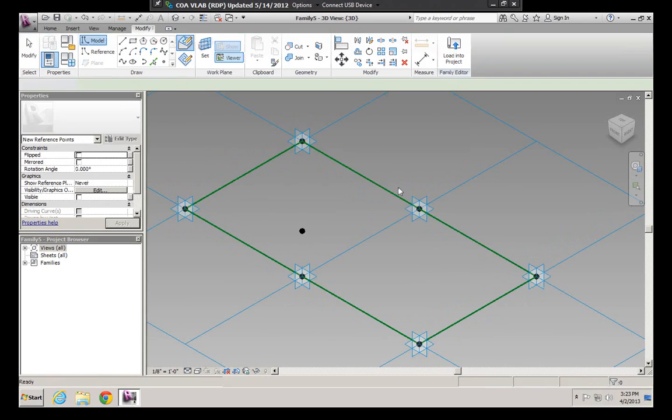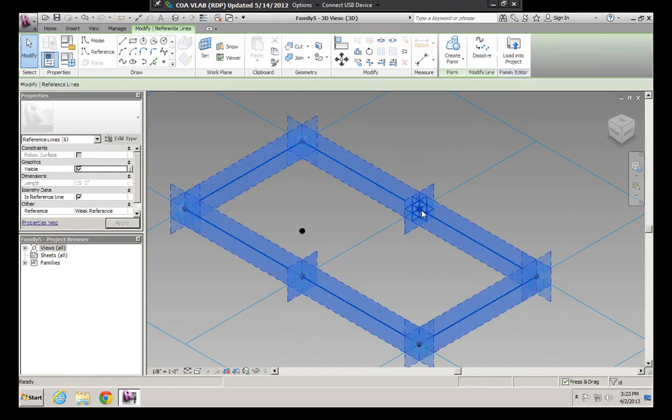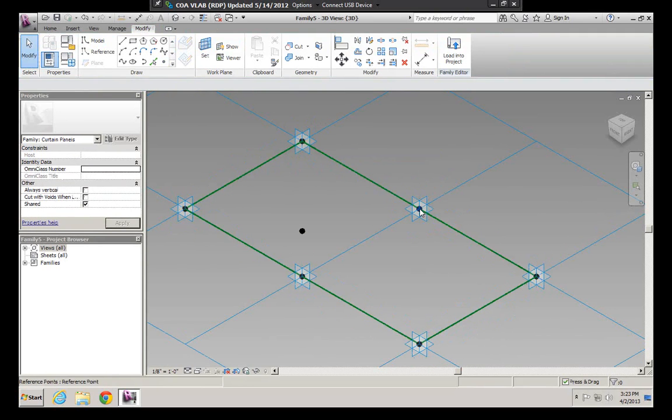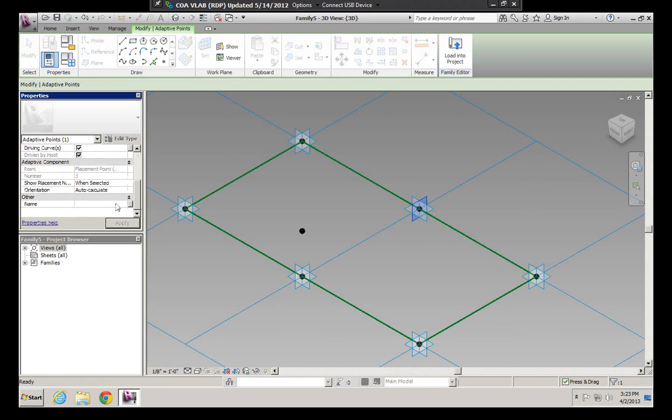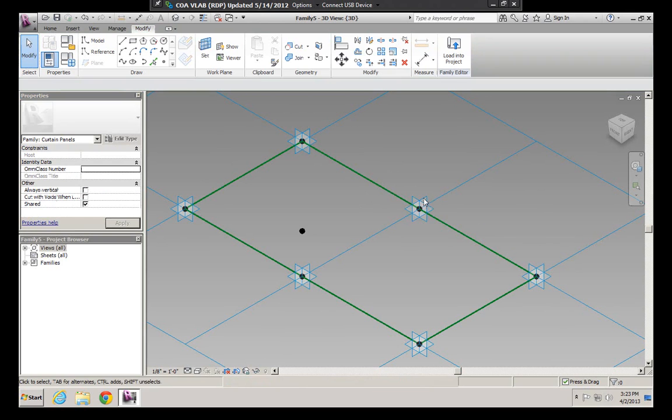Let's go set work plane, this work plane, and place our point. It's giving me an error, so probably there's a point there already. Let's delete that one. Try to find the other point. I think this is the other point. So if I go to the offset value, it doesn't have an offset value, so probably it didn't recognize it. So I'll just delete that point and do it again.